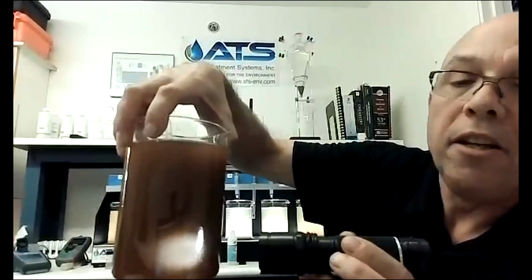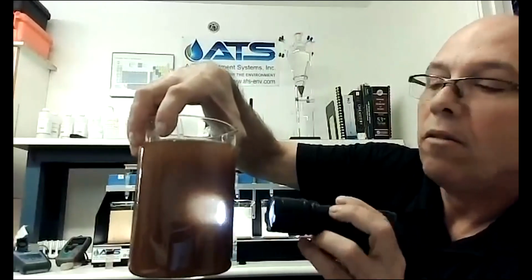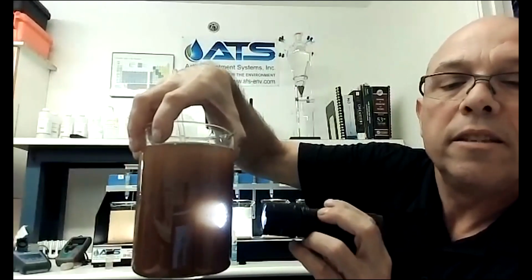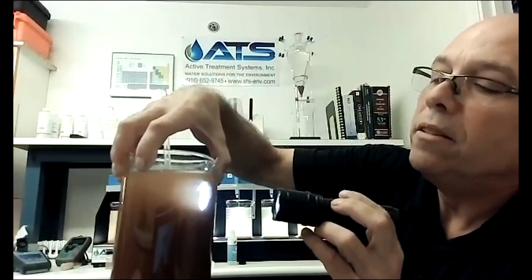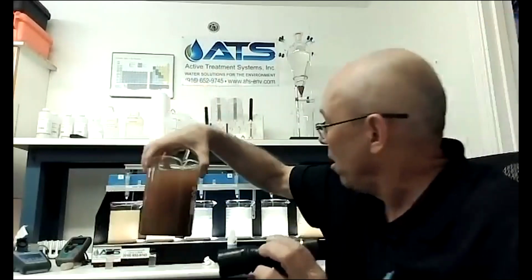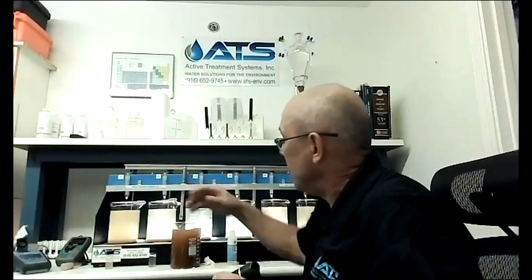All right, now, whoa, look, bring this up a little bit closer and you can start seeing, hopefully you can see that, some floc coming out and settling. And now that's 100 parts per million. I would probably have to mix that again to get the real settling on the top here, just because it takes that much mixing to meet what happens at a static mixer or with my jar test mixer. So that's our field determinations.